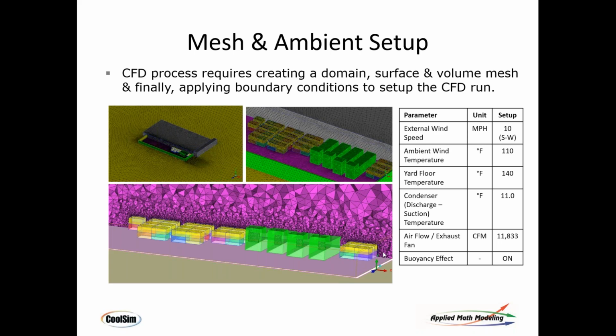Now, how do you know when a certain density is enough? What is the criteria that allows you to understand how dense to make it near the inlets and outlets, Abhishek? Okay. So if we are doing a new problem, then what we would like to do is we make a very coarse mesh, make it finer, see the result, make it even finer and see the result. And if the last two results are within a percentage of each other, we say that the second last mesh was a good mesh. That's a grid independence study that we do. But in most of the cases, after a reasonable amount of experience in projects, you tend to understand where you want what kind of mesh.